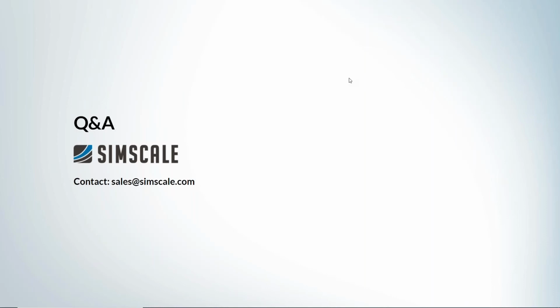That's a good question. We support a variety. SolidWorks, CATIA, plenty of different native files that you can drag and drop into the platform itself. Failing that, if we don't support native, you can always bring in something like a step file, which is a fairly generic CAD format that any competent CAD tool should be able to export for you.